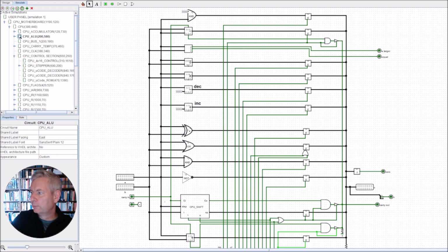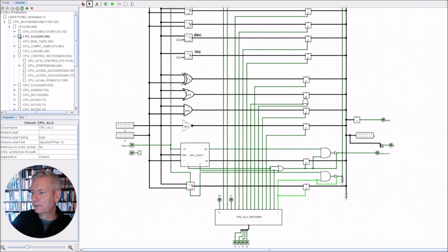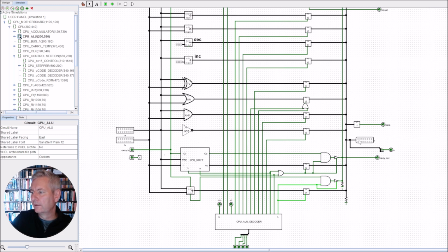We know in 2's complement it's going to be a negative number if the highest bit here on the 16 bits is a value of 1. Then we know that's a negative number. So all we need to do is just take that 16th bit out and test and see whether we get a 1 or a 0. So if this is a 1, it's a negative. If this point here is a 0, then it's going to be a positive.